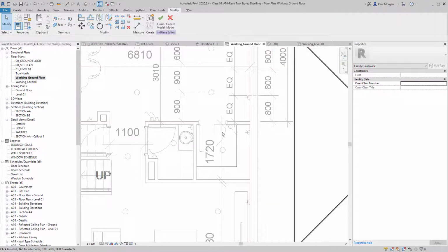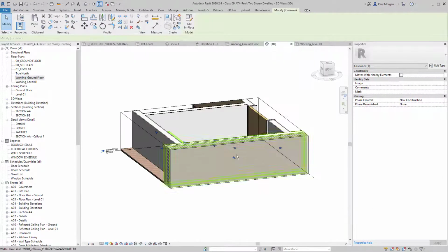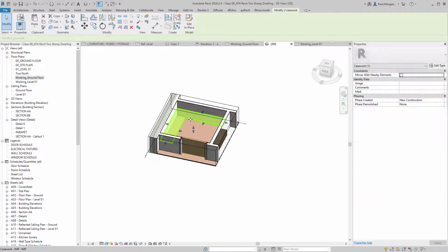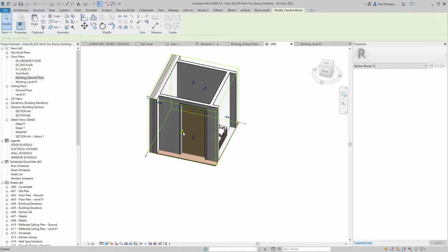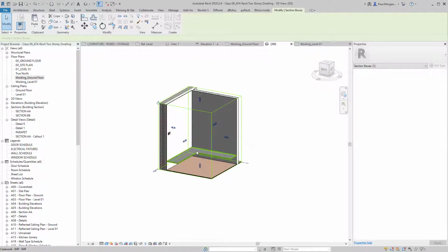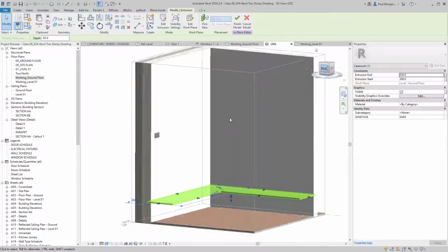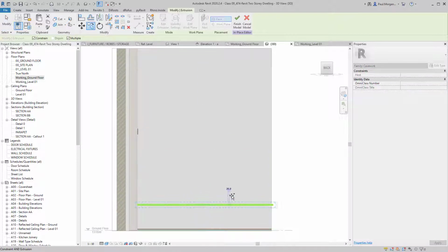Then what we'll do is I'll click OK, and then I'll just go click on this and go BX to make sure I get into my pantry. And in fact, the first one's probably going to be higher than 300 off the ground, isn't it? So I'll just go like this, move this back here, move this back here. Double click to go back into the family. And I can even just use any of my views, like my back view or left view. I can just copy these literally just from one place to another.